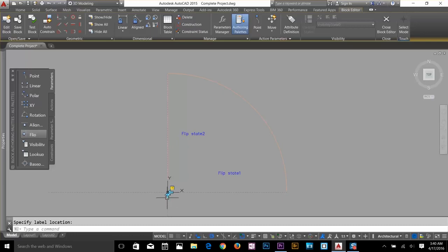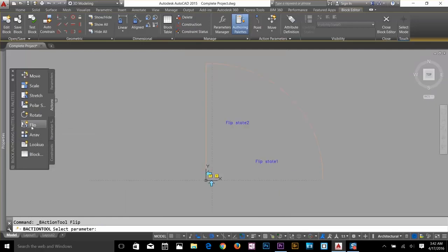And just make sure that these arrow buttons change that about here. I've got one flipping parameter here, I've got one flipping parameter about here. So go to your actions and click on flip, select this parameter, and then select an object, and that's it. You got your flipping parameter done here. And now I'm just gonna move it a little bit up and click on flip again, click your parameters, select an object, enter, and you got that there as well.